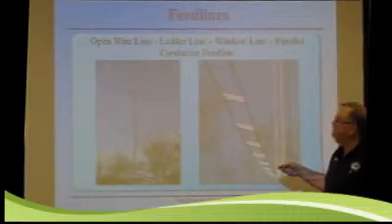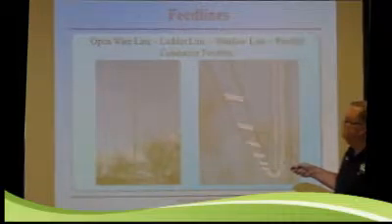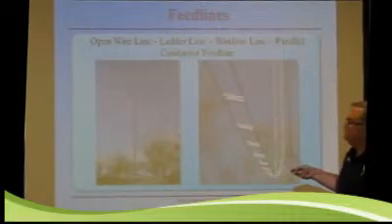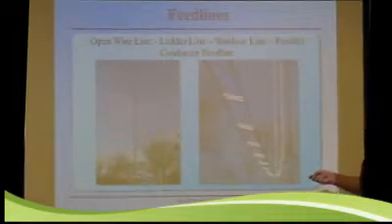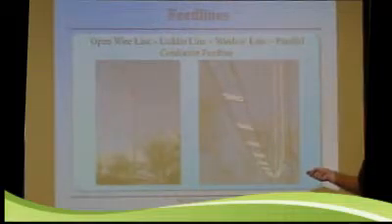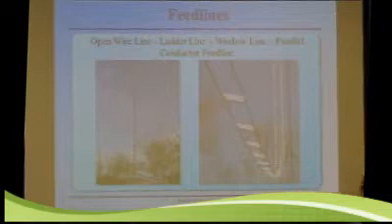Those of you that may remember the old twin lead type wire that you used for old TV antennas, this is something similar to that, except they knock out little areas. They call it ladder line or window line, and it's like open wire, except it's fully insulated. But you still can't put that next to the tower leg, or if you do, there's problems that will occur. It needs to be kept about 3 times its width away from metal. So if you've got a 2-inch wide window line, 6 inches away from anything.